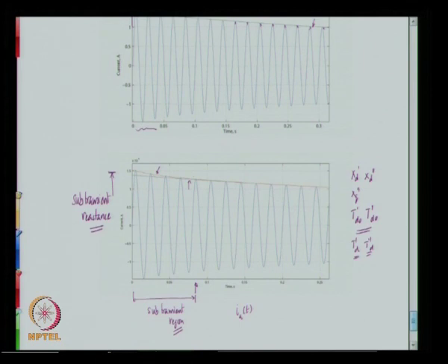If we do a simulation of the alternator equations when subjected to a short circuit, one can solve the differential equations using a suitable numerical integration algorithm, using which we can evaluate all the variables id, iq, ikd, ikq, and if also. We can estimate how the field current is going to behave. So all these will give us useful information about the behavior of the circuit.